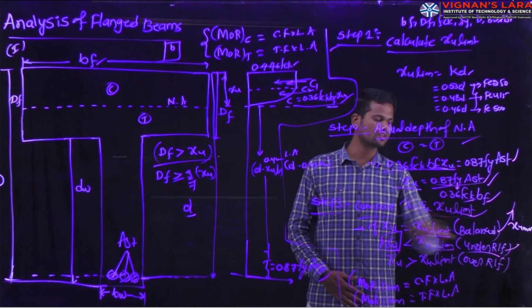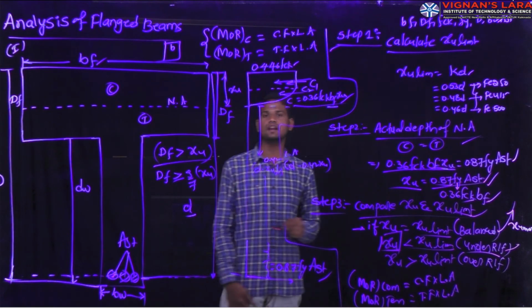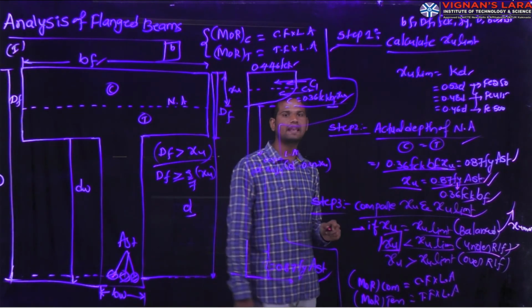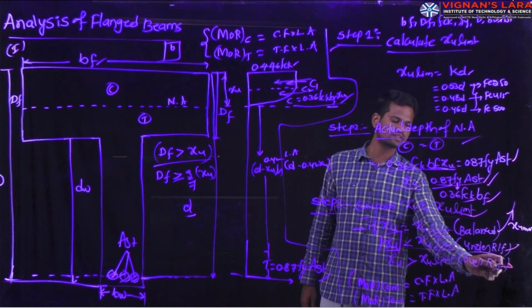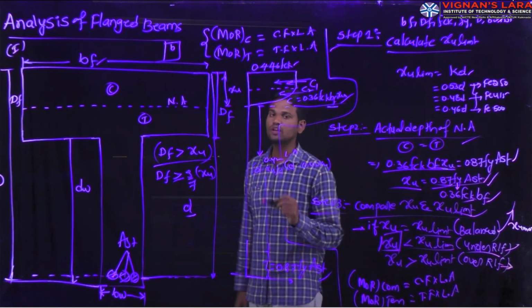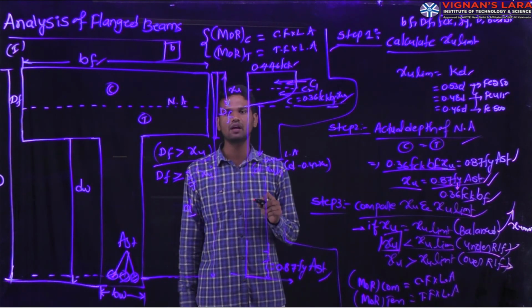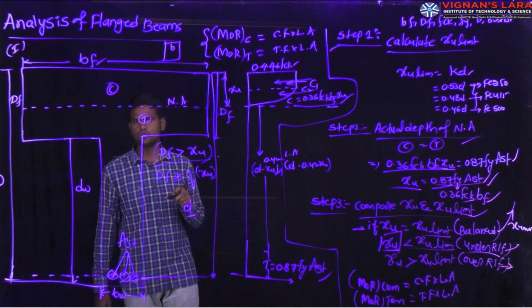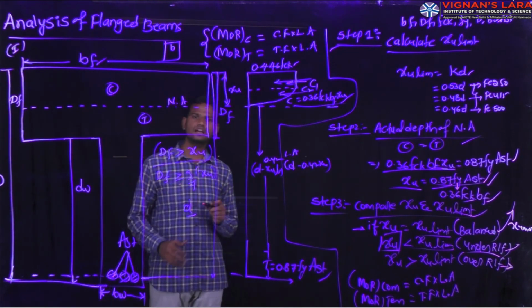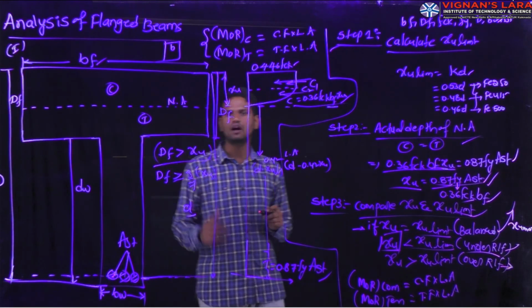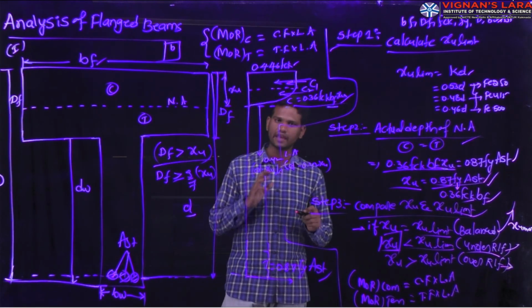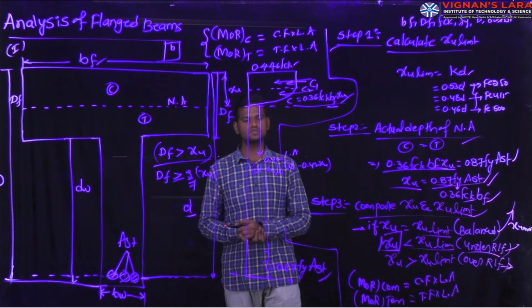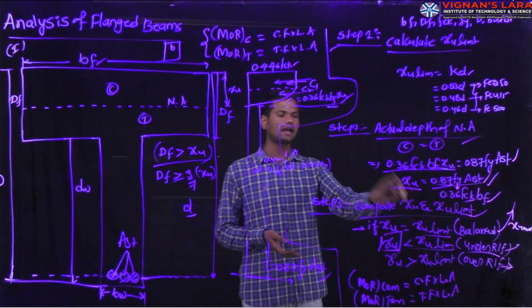Whereas if you consider the under reinforced section, we are providing less steel compared to the balanced section. In the over reinforced section, we are providing more steel compared to the balanced section. Due to the provision of more steel in the section, the concrete area may get reduced and concrete will fail first. It won't give any alarm, hence we won't use any over reinforced design section. This is the comparison of XU and XU limit.